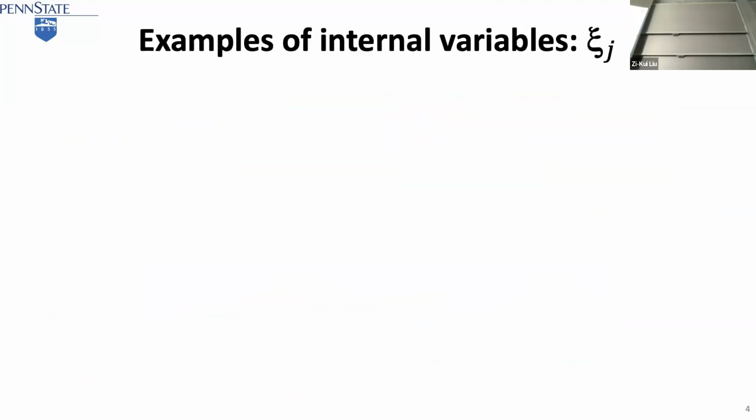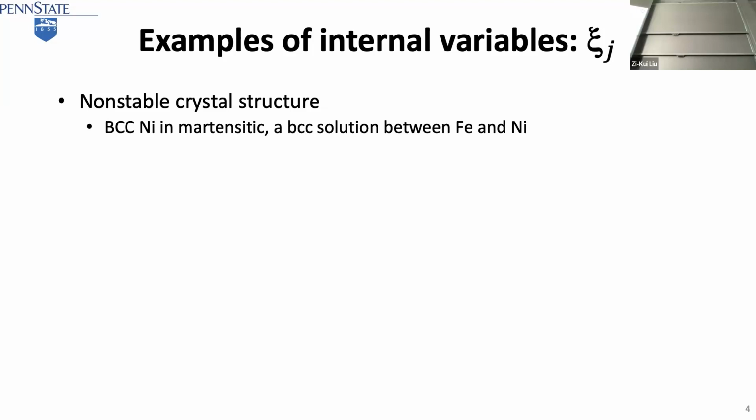All right, so getting back, I want to focus on the CALPHAD. Remember the French company, CALPHAD, right? That was when Larry Kaufman realized that challenge. He was working on martensitic transformation. He wanted to model iron-nickel, right? We know iron is BCC at martensite, but nickel is never BCC, right? Now he needs to put nickel into BCC in order to model martensite. He asked, I need a BCC nickel. The answer was crazy: he says no, nickel is not BCC, you cannot do it. It was debated at that time. The big names said you should have to access nickel, forget about BCC nickel.